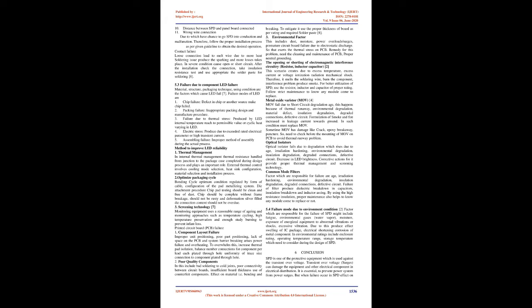Contact failure. A loose connection leads to melted wire due to more heat, and soldering issues produce sparking and more losses. In severe conditions it causes an open or short circuit. After the installation, check the connection, take an insulation resistance test, and use the appropriate solder paste as a soldering aid.